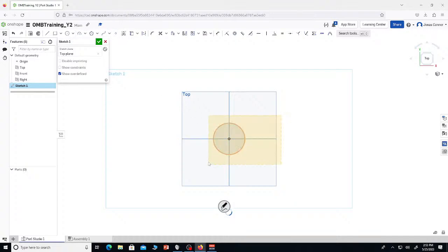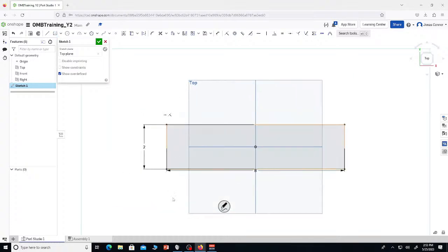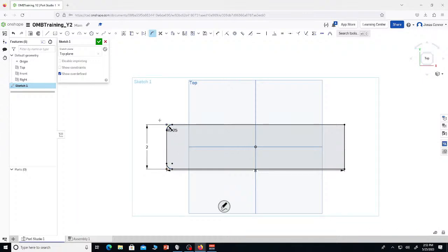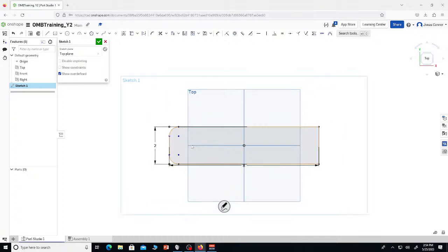3-point arc. So let's say I had a bar that was like 8x2, and I wanted to make this corner smooth. What I could do is fillet it using this tool right here. I can fillet this down, hit enter again, and then edit this radius right here and make it, you know, 1/2 inch, whatever. Or I can get rid of that fillet, Control Z, Control Z, Control Z, Control Z. I can Control Y to redo.